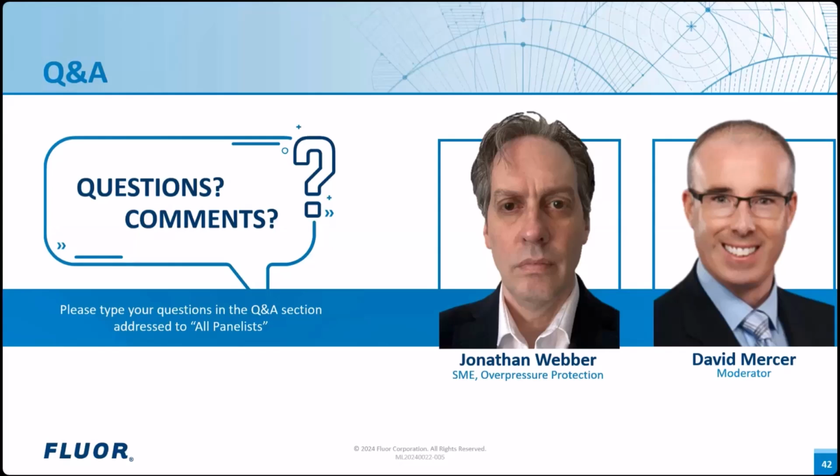Without getting into specific costs, generally HIPPS systems are more expensive than the PSV. However, in many cases you are installing the HIPPS only because the PSV is ineffective, so there's not an option. You have to go to the HIPPS. But the other side of the cost is the impracticality of expanding an existing flare system. Every case is different, but in many cases, the cost of debottlenecking the system would far outweigh the cost of a HIPPS.